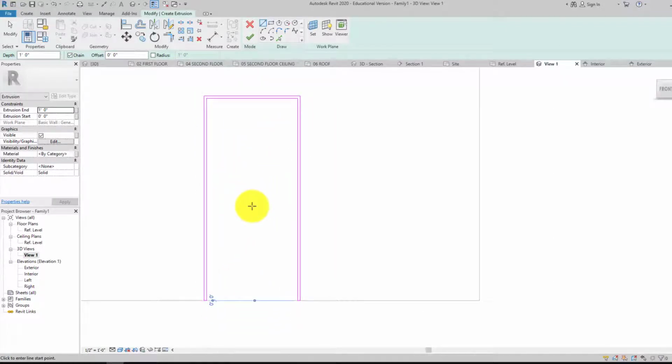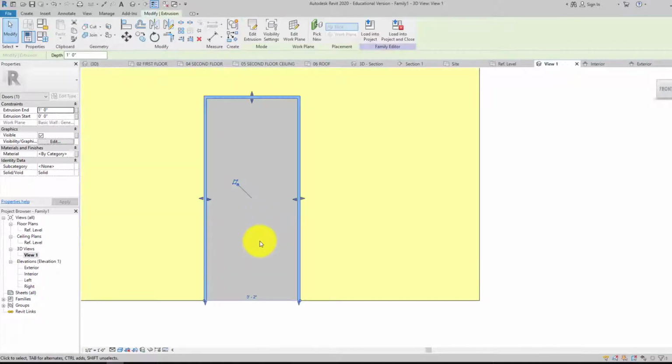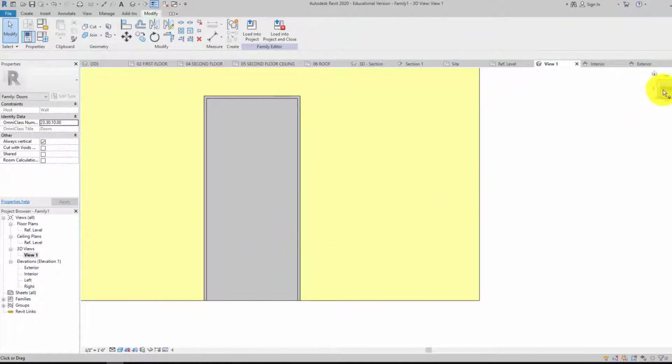So, again, in Revit, you cannot have any overlapping lines. I'm going to hit escape and just show you this is the geometry. It's got to be perfect. It can't have any overlapping anything. If it does, you'll get an error, and the geometry just has to be a completed perfect box or whatever shape it is. Alright, so you can go ahead and click OK.